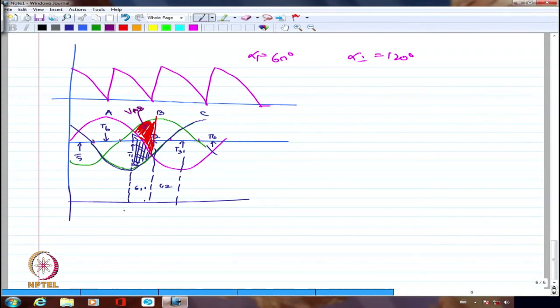So I am going to get some voltage like this continuously. Please compare that voltage with this voltage. Average value will be the same because I am inverting this. It is connected the opposite way because VD2 is connected with positive terminal to the bottom and negative terminal to the top. So exactly the opposite connection I am making.